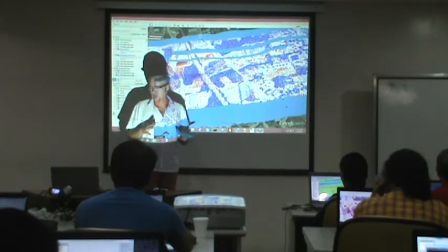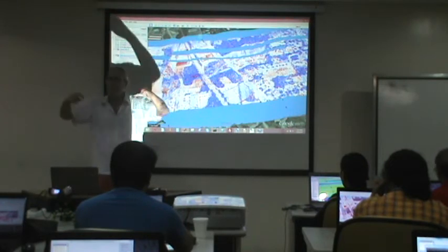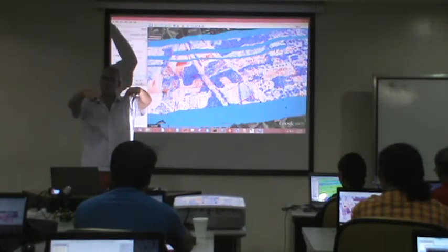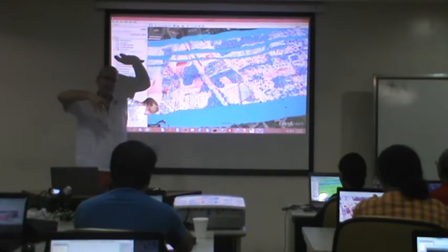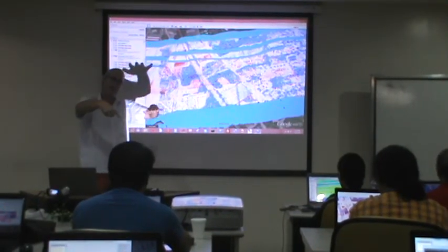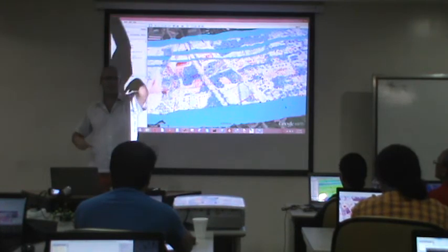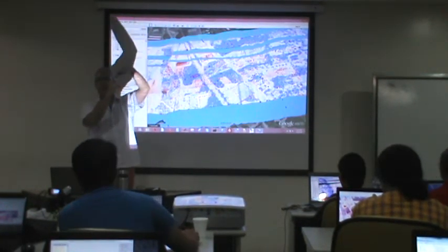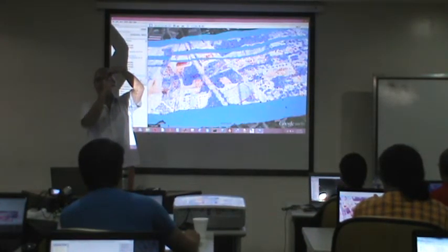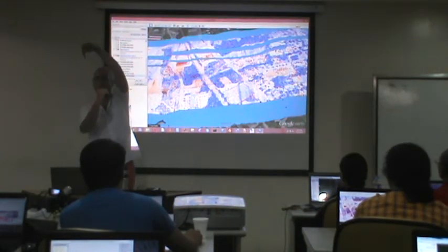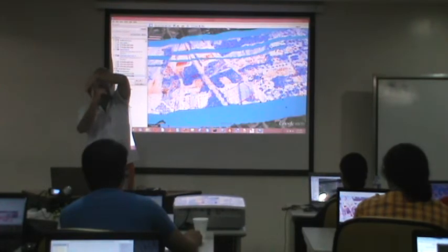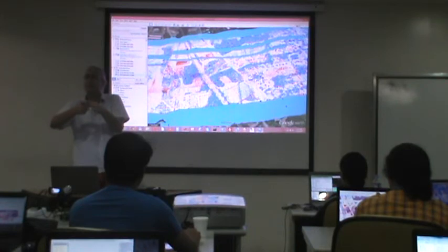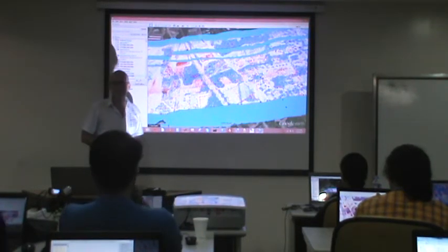It can also not indicate a mistake at all, but remember the scanner is looking from a slightly different angle. So the one flight line sees the building from this side, and one flight line sees the building from this side. So if there's an edge, this scan hits it here because it doesn't see the area here, and the next one can see all the way to the ground. And then they have basically the height of the building as a difference in that particular 2 by 2 meter area.